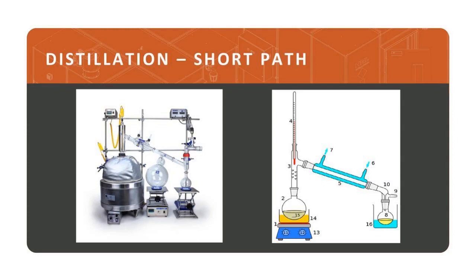Then we do have a thermometer up there at the top, checking the temperature at the head of the Vigreux tube. That's a very critical point in the process because it's going to define which compounds remain gases at that point, and we'll be able to travel past that. So you really want to control temperature right there. That might be the most critical temperature control point in the entire system, even more than the crude oil bath that we have at the bottom.